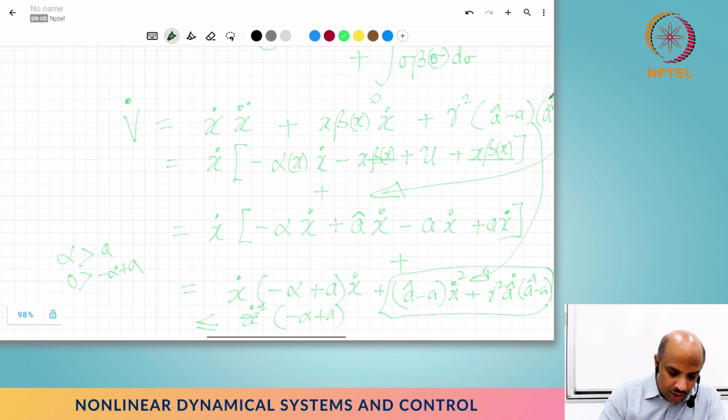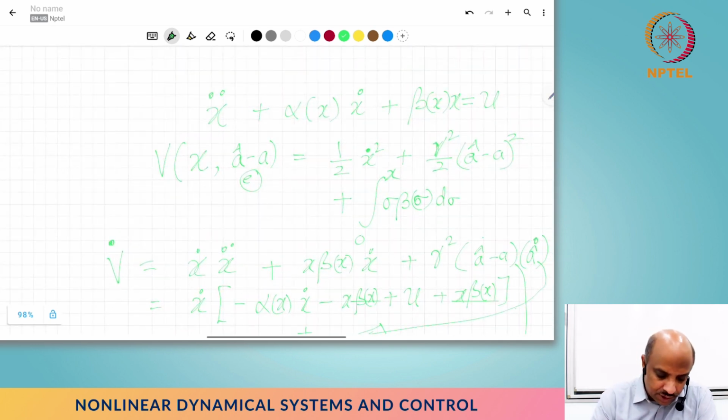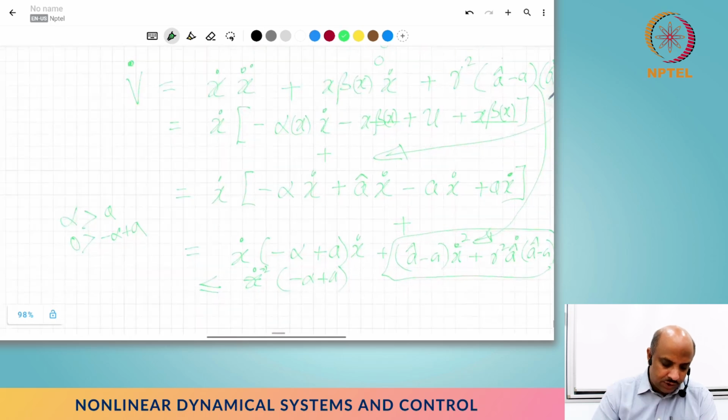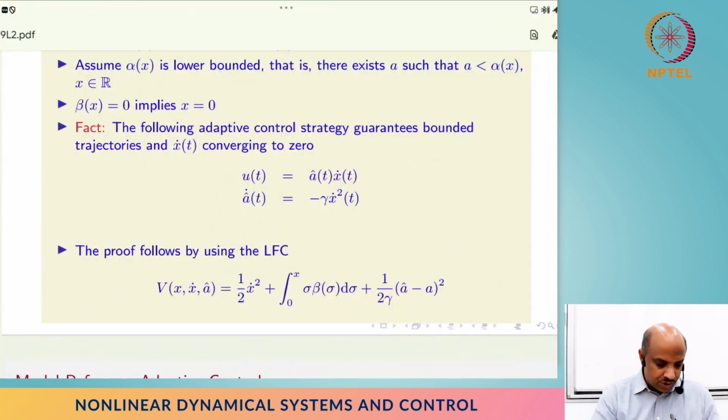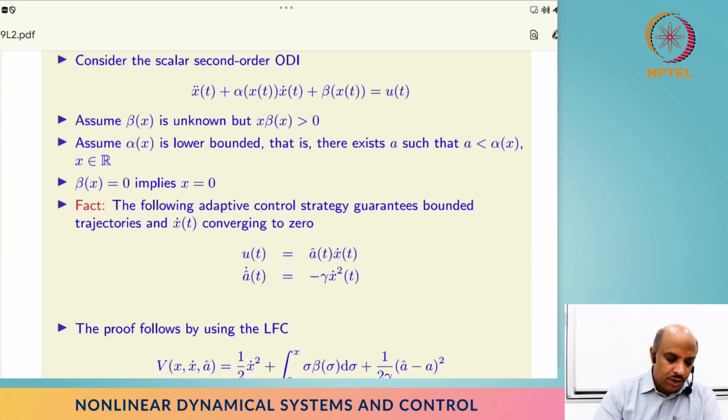Right? So again, going through the same logic we have been going through multiple times. Basically this entire thing can be shown to be bounded, therefore each one of those variables can be shown to be bounded eventually using that fundamental result in mathematics that we showed. X dot is going to go to 0, and then using zero state observability in this particular case we can show that it is zero state observable, and the fact that beta of x is going to be 0.